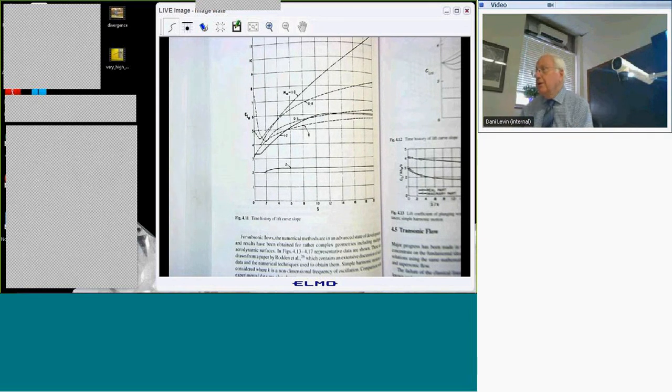So that disturbance at Mach 1 created by the motion of the wing or the airflow never gets off the wing. And in some sense, it builds up so that the linear theory breaks down at large time. But at short time, you probably get a decent answer. Or at least you get a finite answer, right? That's better than infinity.